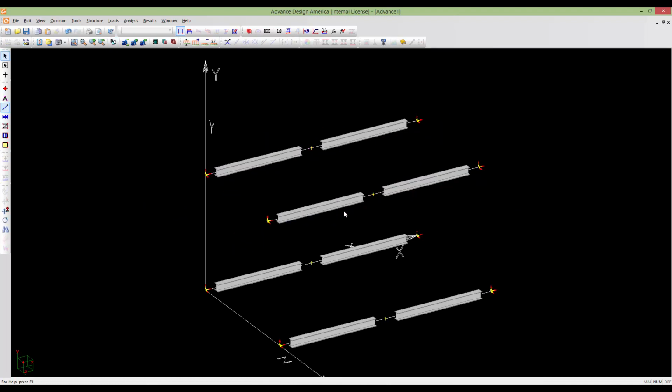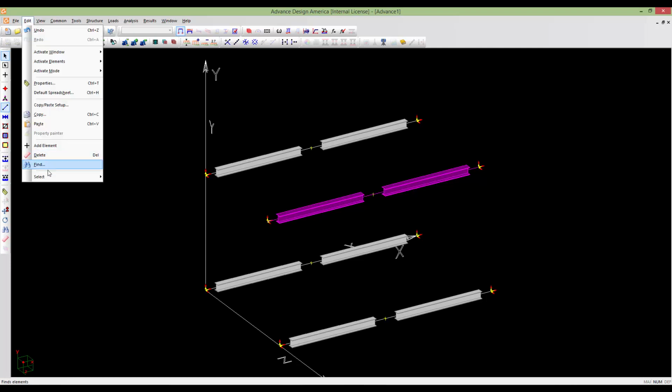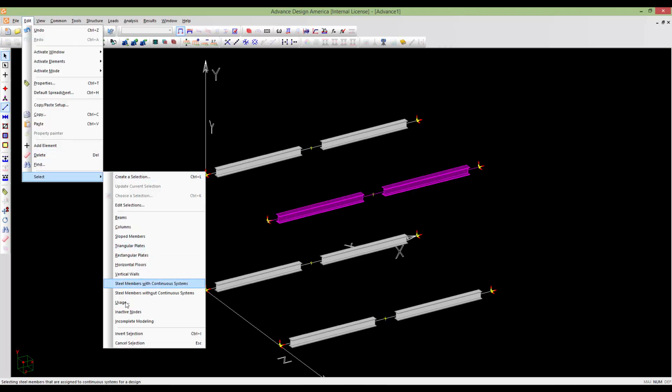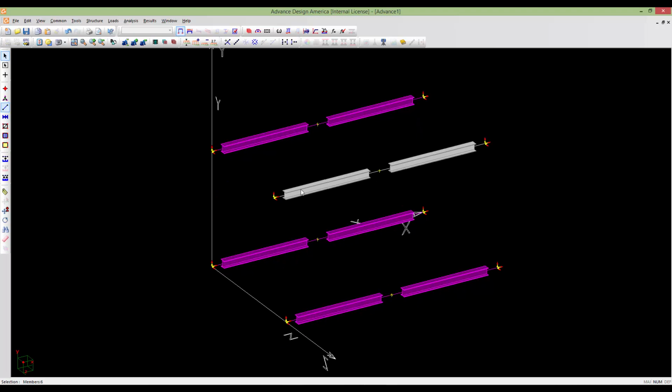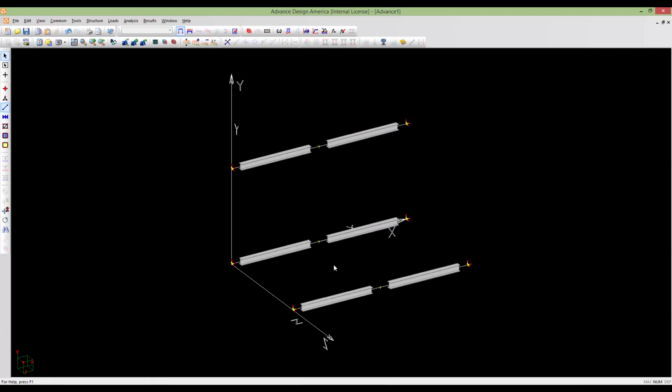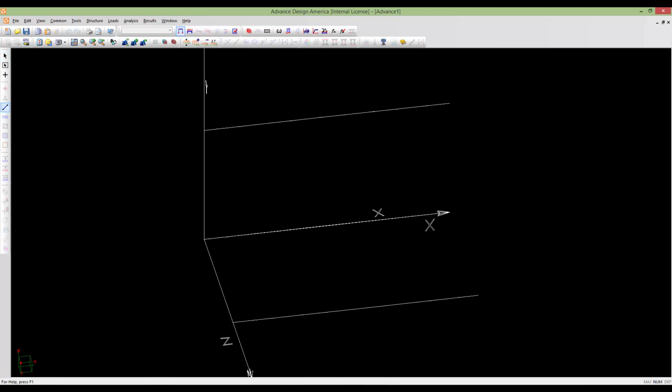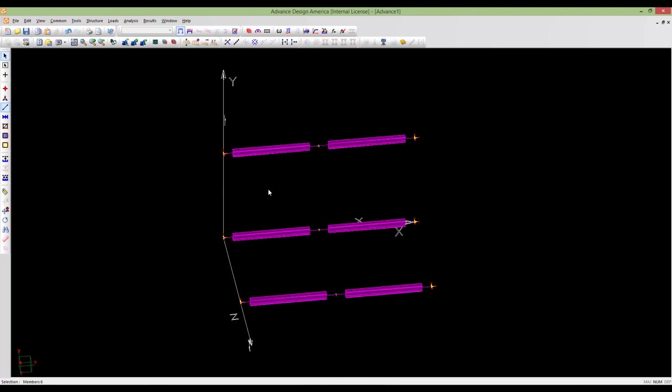Also, we have the option of inverting our selection. For example, you can select these and hit I, and go here and invert selection, as you see, or Control I. All of the selections will be inverted, and right now you can mask that member and keep the other one. So you have two ways to mask your member or your element to work on.